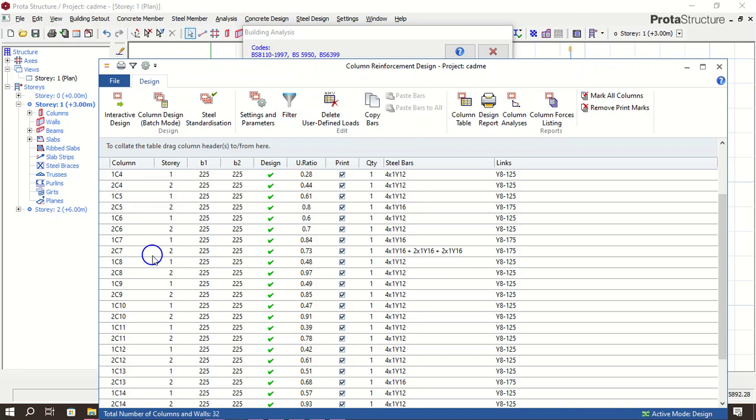But when you come to your roof column, you end up having even more reinforcement for the same column that was okay, and you'll be thinking, this is the same column that was carrying a smaller reinforcement with even more load. Why am I now having the same column on the roof, that is not even carrying much load, having so much reinforcement? The reason is simple. When the column is subjected to more moments than axial forces, you're going to be having those problems, because the column has to select reinforcement that will counter those moments.